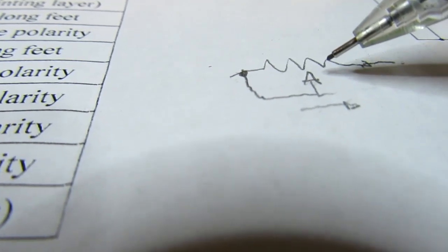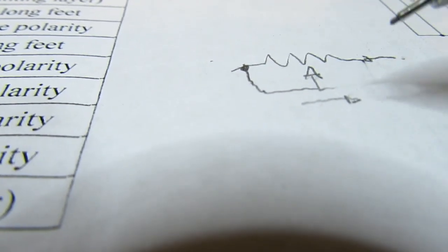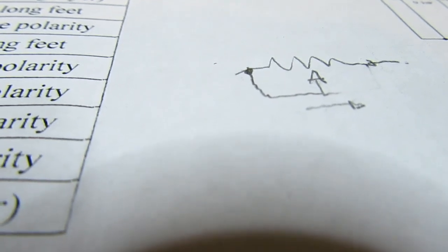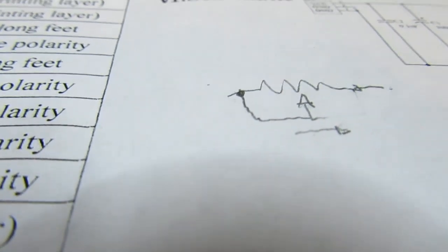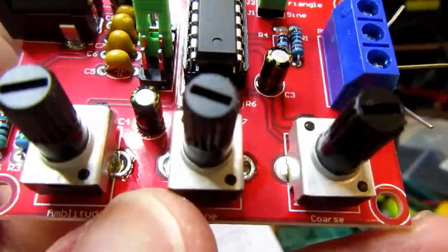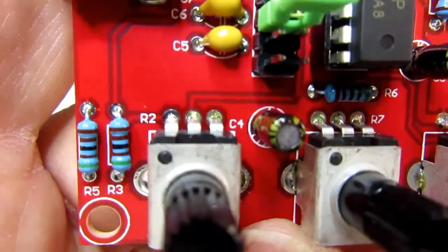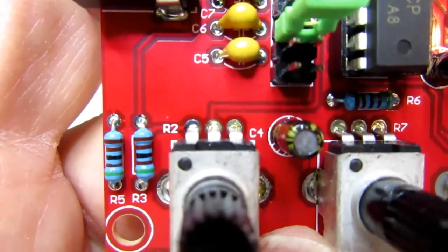It actually decreases the resistance as you move it clockwise. So that's the only thing that really should need to be adjusted on this, and it's pretty clear from the circuit board foils that the wiper of the pot does come off the middle.